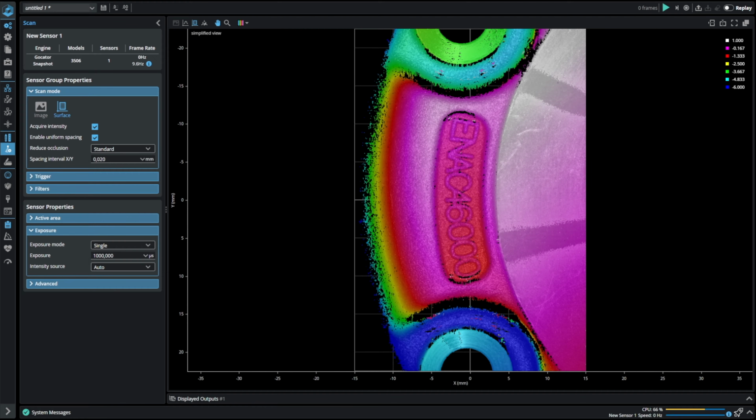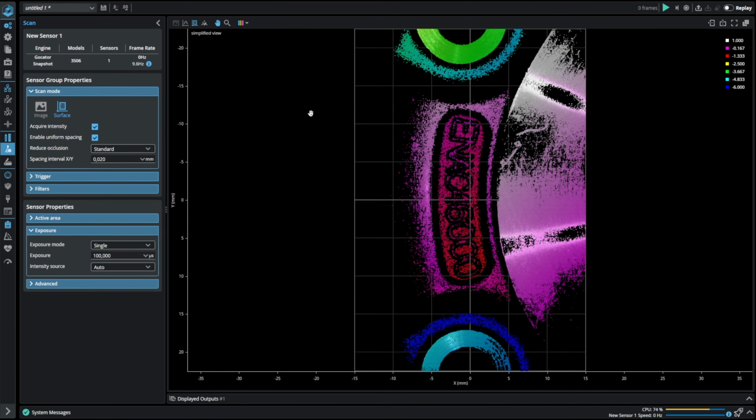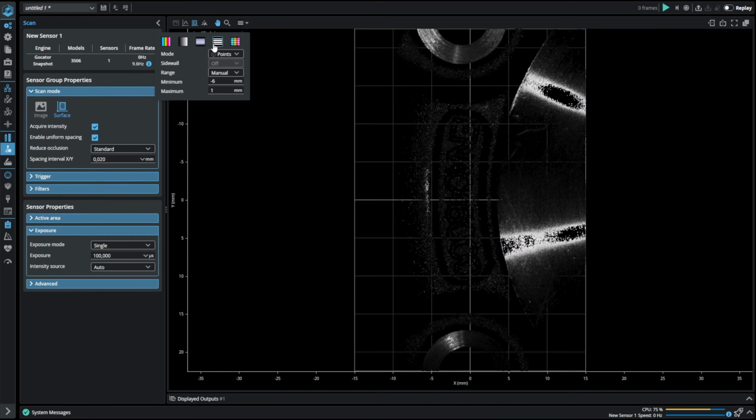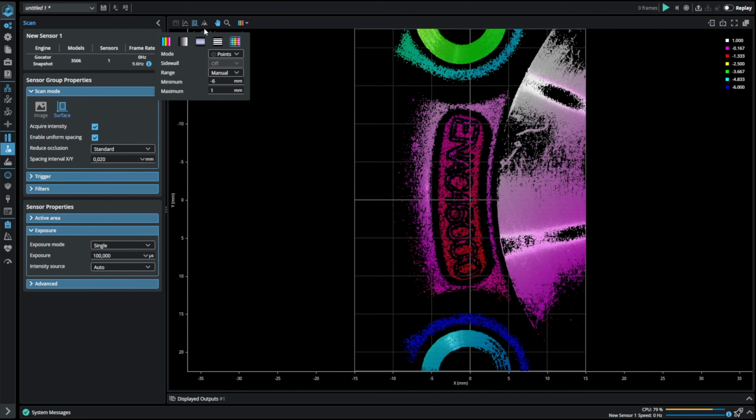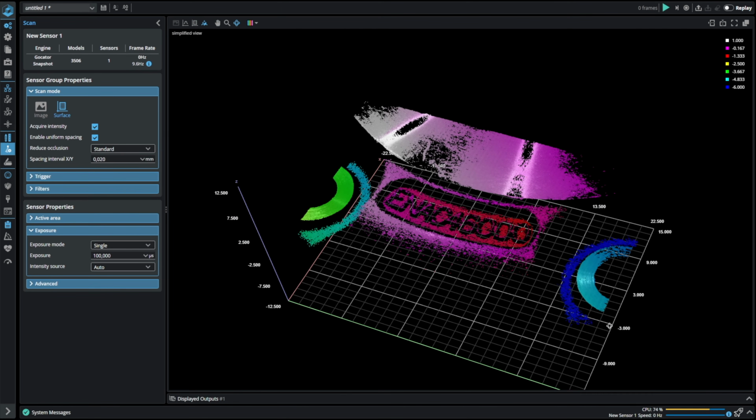Let's go back to the surface scan mode. I always recommend starting with setting the exposure time from the shortest to the longest and checking the data quality along the way. This process will give you a good feeling at which point the data are underexposed and which overexposed. Start with 100 microseconds. As you can see, this data is underexposed for most of the surface. Nevertheless, the very shiny surface gives us a good response with this exposure time.